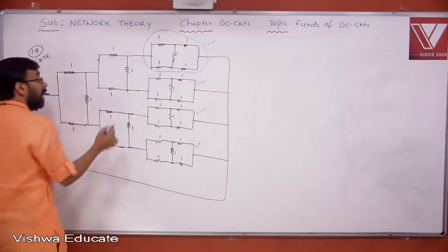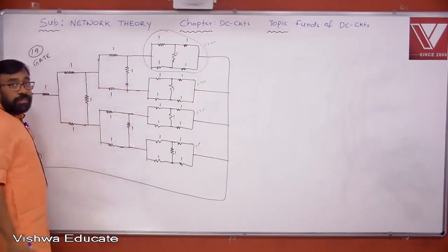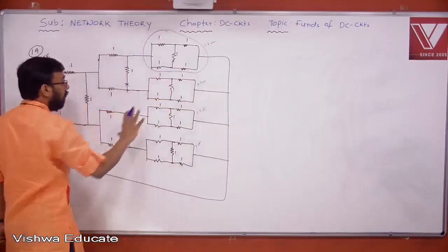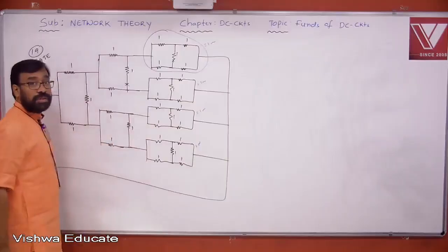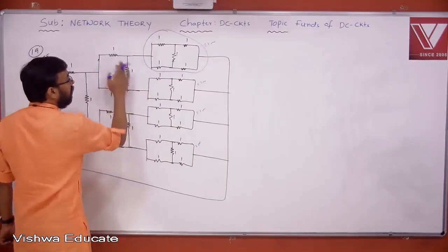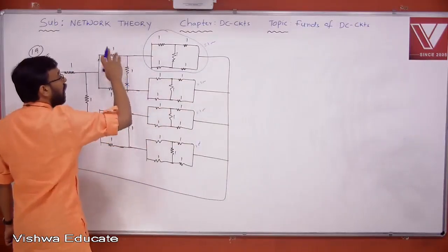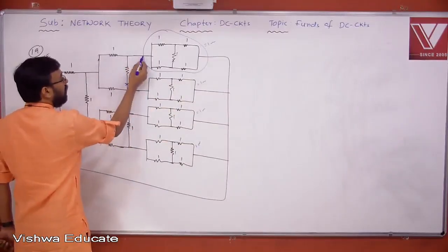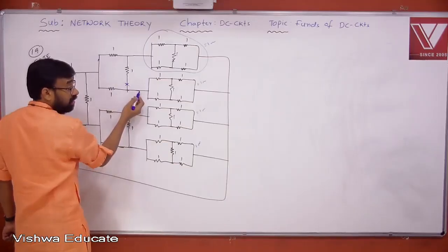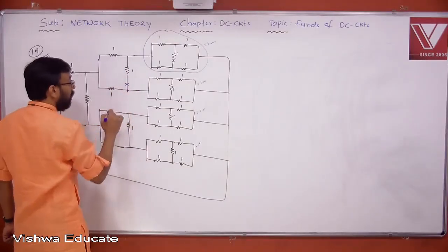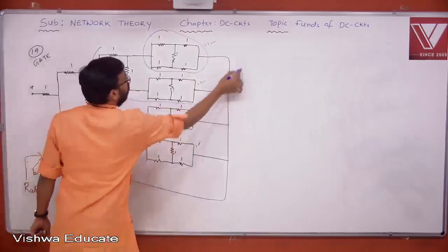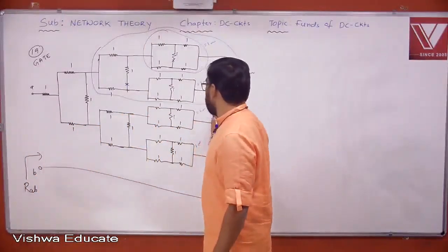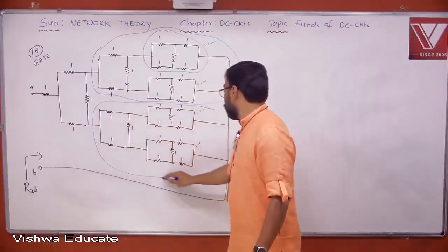So, what is happening here? Again, this is neglected. And the similar section you are observing here also. The same kind of arrangement is available in this particular section also. So 1, 1 and 1, 1, and this is again forming a Wheatstone bridge, and that is a balanced one. You can neglect it. Then what happens here? Tell me. 1 and 1 are in series once you neglect it. That is 2, 2 parallel to 1 again. That means this entire portion is becoming once again what? 1 ohm. If this is 1 ohm, this is also what again here? 1 ohm.